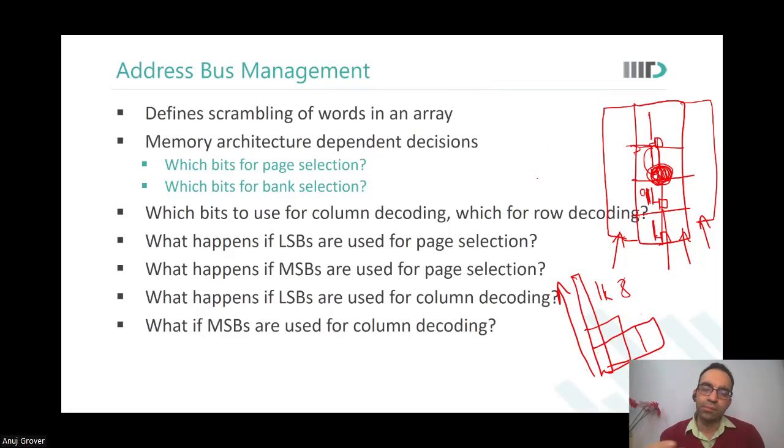Sir, in this case our bank, the whole column, instead of one long bitline we broke it into multiple bitlines, meaning different parts. This is called hierarchical bit line. And sir, we made each bit line capacitance smaller. So each bank will correspond to a certain set of bits of a certain set of words. Some words will come in one bank and some of their bits. Yeah.